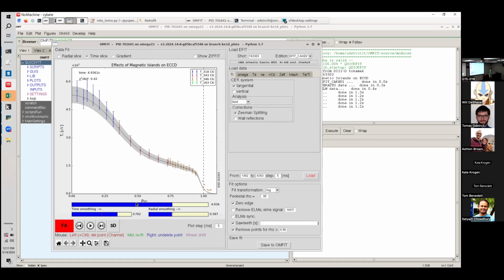So yeah, another issue with the experimental data is that there are often some outliers. In this chart, there are not, but if you have outliers, you can follow the simple help below: select, using the left mouse button, the point which you want to remove, or the right mouse button, and you can undelete the points.